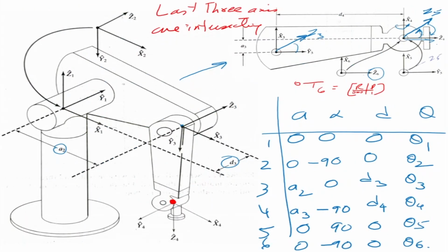So if you look at the manipulator structure and you look at the DH parameter table very, very carefully, we see that the 0 and 1 axes are here. 0 and 1 is here. 0, 1 and 2, all three are here. The origins of 0, 1, 2 are there. They are the same point.